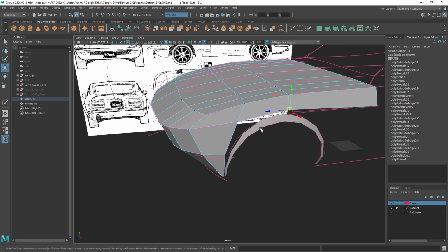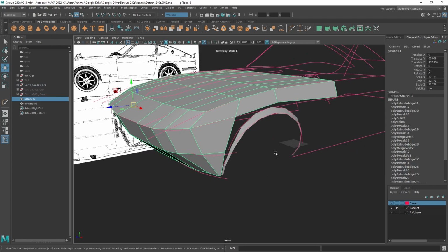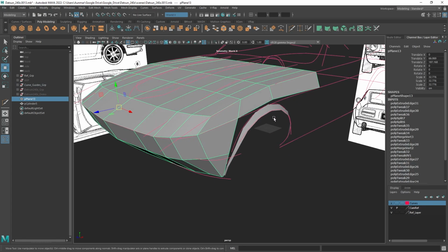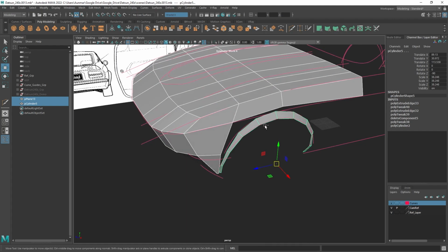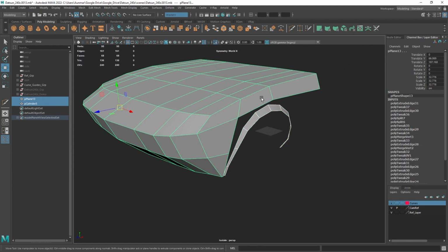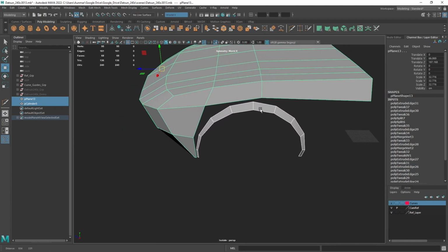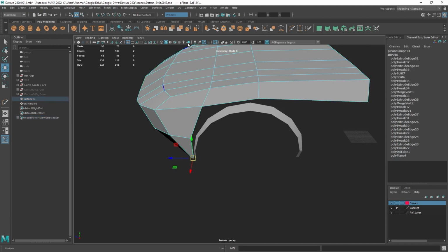Because I wouldn't want to just manually try to edge copy this wheel well form based off of this geometry. It's just too blocky and will cause a lot of tweaking, lost efficiency. So instead, I started with the cylinder and worked from there. I select both of these, hit Control-1 to isolate, and we can work from here. And we can start matching the topology.